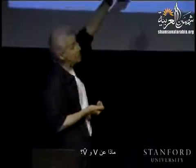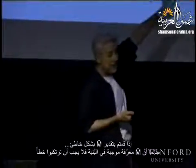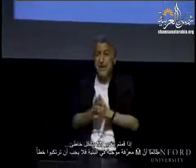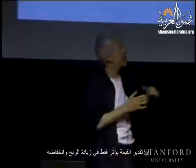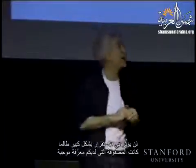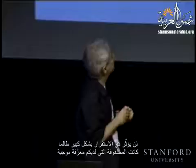What about V and V hat? So if you make a mistake in the estimate of m hat, as long as m hat is positive definite from your structure, you shouldn't have a problem. The effect of it is just scaling your gains up and down. It's not going to affect the stability too much as long as you have a positive definite matrix. What about V? If you make a mistake in V hat.